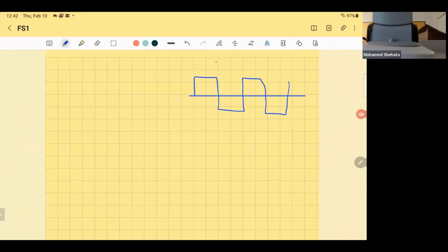And that's the x of t signal, a square wave. It doesn't have to be symmetric. It's periodic; the condition just has to be periodic and finite. Okay, so we can do it like that. We can say it consists of a DC component. Let's call it x naught, the DC component.